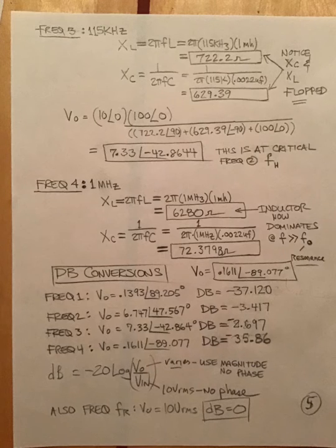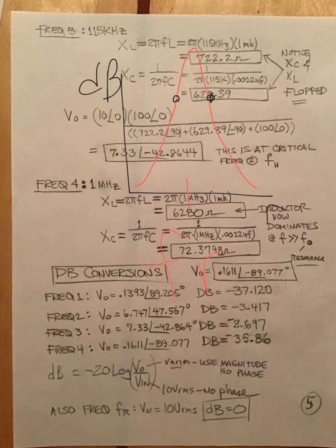If you forget what a bandpass Bode plot looks like, you're going to be plotting for a resonating frequency at some value with a couple of cutoff bands, and we want to plot dBs versus frequency, and we're going to use semi-log paper to do this. And so the starting point for any of these problems is you have to solve an initial circuit.